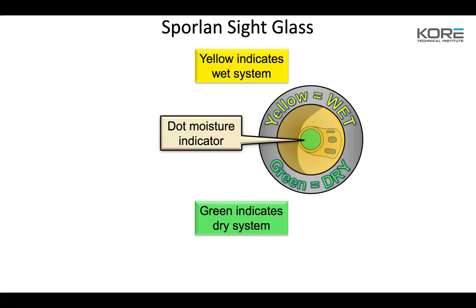So if you're doing some work and you're trying to get non-condensables or contaminants out of the system, and you do have a yellow sight glass, you want to make sure that when you come back to do your change-outs, you're turning that back to green. If you cannot see through the sight glass because it's old, just change it. So next time you pump it down to change your filter dryers, let's change the sight glass too.